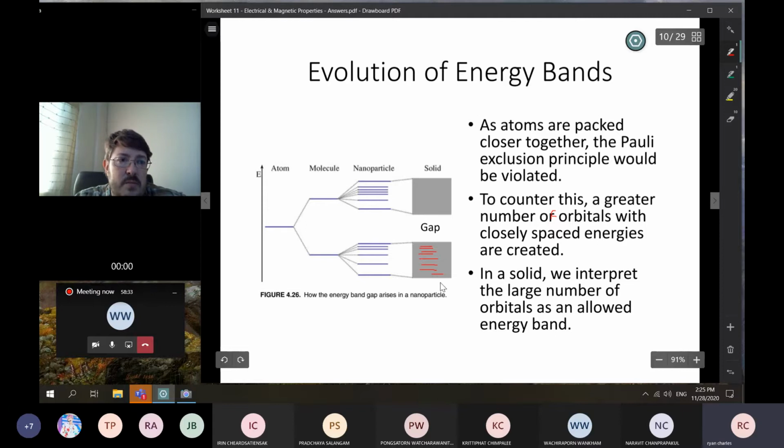There's a whole bunch of states in here, right? This was down below the gap. We care about the ones that are up here. What's the density of states up in the conduction band? How many little steps do we have? Each little step can hold an electron. So that's what that NC is. How many little bands are in there, right?